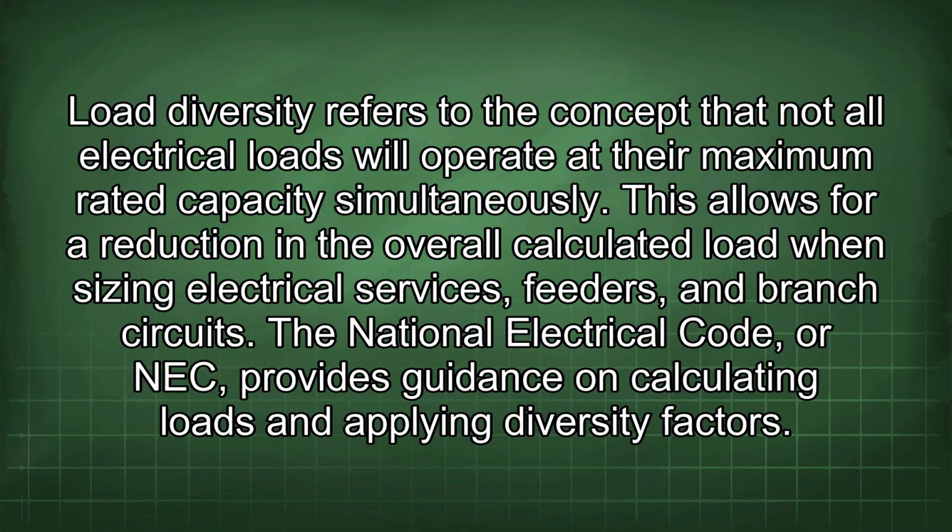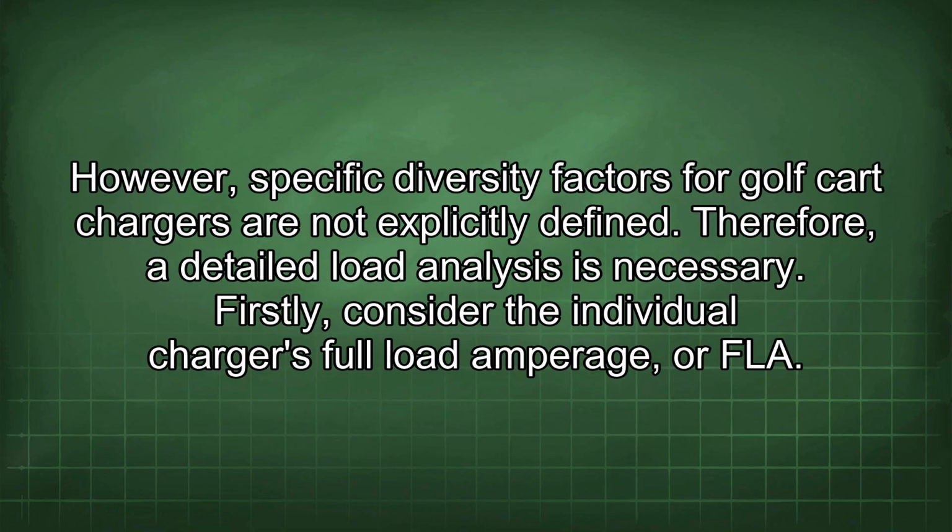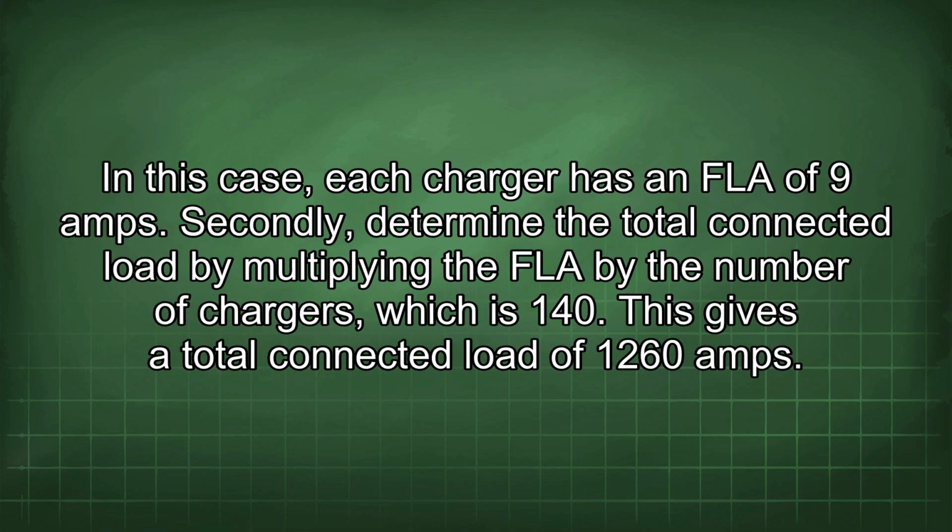The National Electrical Code, or NEC, provides guidance on calculating loads and applying diversity factors. However, specific diversity factors for golf cart chargers are not explicitly defined. Therefore, a detailed load analysis is necessary. Firstly, consider the individual charger's full load amperage, or FLA. In this case, each charger has an FLA of 9 amps. Secondly, determine the total connected load by multiplying the FLA by the number of chargers, which is 140. This gives a total connected load of 1260 amps.